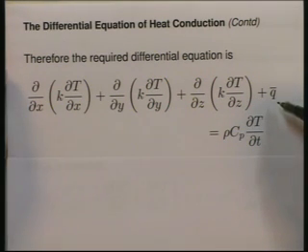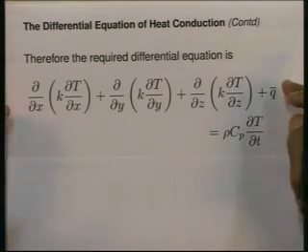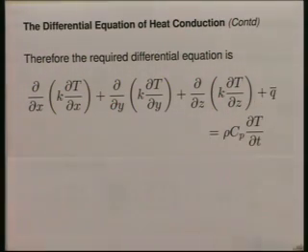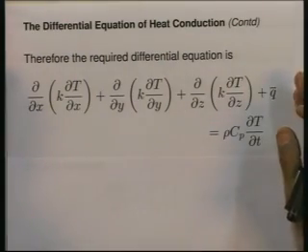This is a situation in which we have an isotropic material, we are working in a Cartesian coordinate system, all right. T can be a function of x, y, z and time, that is why we have a partial differential equation, and there may be heat generation q bar which may be varying or which may be constant, whatever it is, it will be some specified amount. So, this is the most general form of a differential equation that we have got.